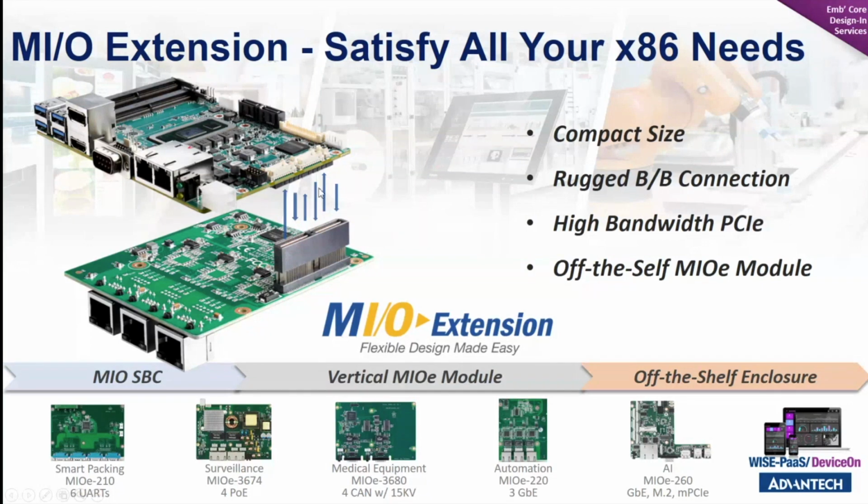This high density Semtech connector carries certain signals like PCIe, LPC, or USB, which we can use to convert to other things. Then you create a daughter board and connect at the base to expand. Okay, why is this very useful? You are taking a ready board, everything manufactured already, everything can work.